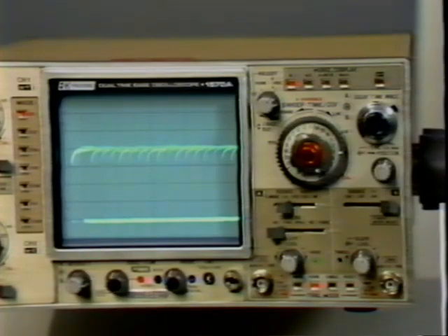As you can see, the output of an address or data line does not produce a clear, stable display. This is because the voltages on these lines do not have a set frequency or period. In order to determine that the line is working, we merely observe that it can produce valid TTL highs and lows. We don't know that the data being produced is the correct data, only that it has valid levels.